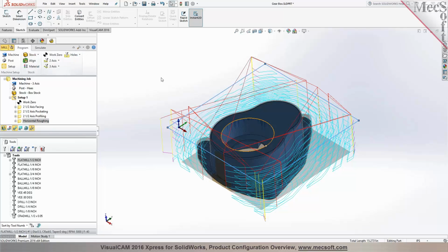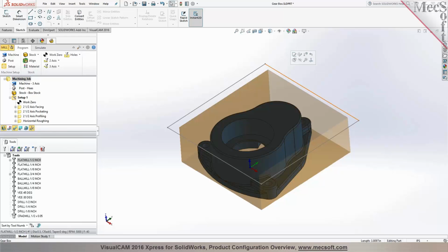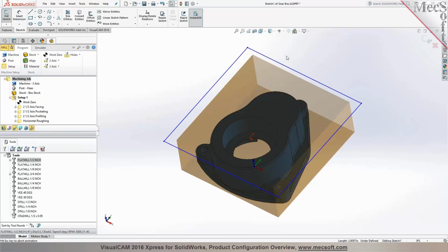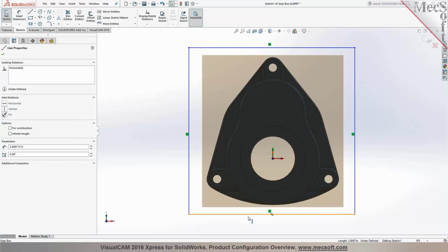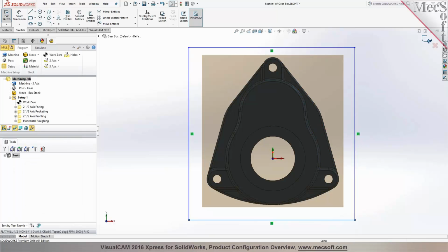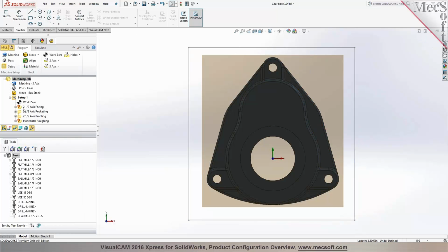Now if you'd like to go back and modify your sketch or containment, since you're working in a parametric system in here, I'm going to go ahead and edit the sketch. And I'm going to go ahead and resize it. You'll see that I'm going to modify the sketch, make it slightly wider in here. And I'm going to accept the changes, commit the changes. You'll notice that the operations that utilize the sketch were automatically flagged as dirty in here.